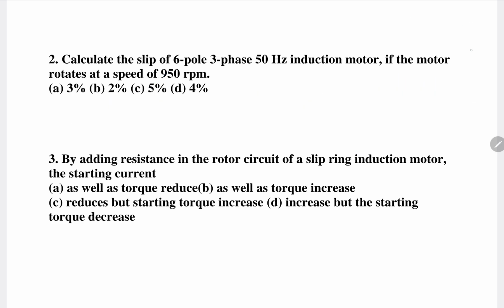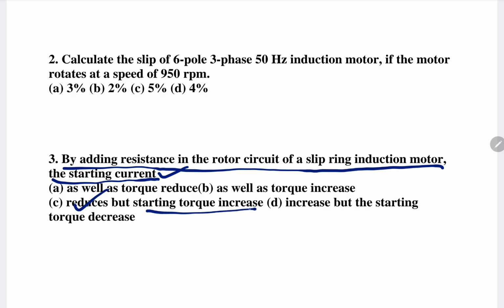Next, by adding resistance in the rotor circuit of a three-phase slip ring induction motor, the starting current is going to reduce and the starting torque is going to increase.